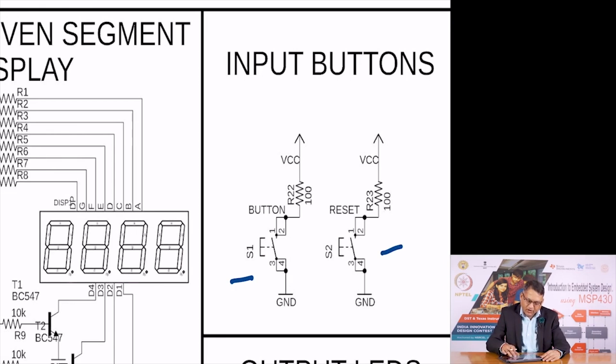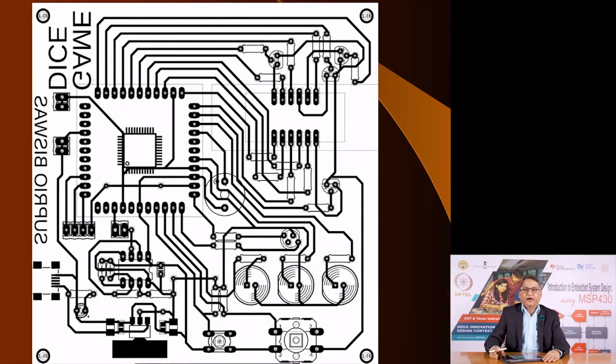Here is the board layout. This was fabricated in my lab on a single sided board. Now, the CPLD itself is an SMD IC, which has very fine pins, and it was not deemed possible to fabricate a circuit to accommodate such a fine pitch IC. And so, an interesting approach, as I had mentioned earlier, was taken to create a breakout board. This is the breakout board.